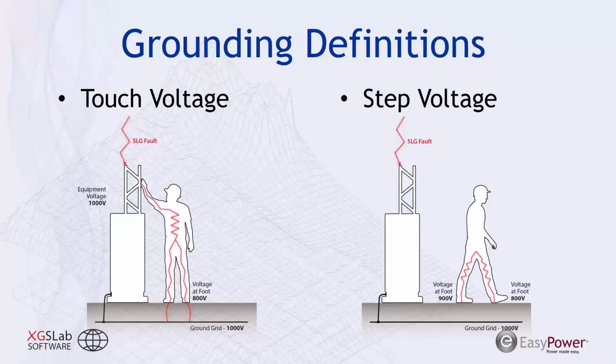And I do want to mention that there is a standard, IEEE 2778, which is very related to this grounding analysis. It's the IEEE standard for photovoltaic systems. What's provided in that is more of a how-to, or different techniques and methodologies for performing a study for a grounding system.